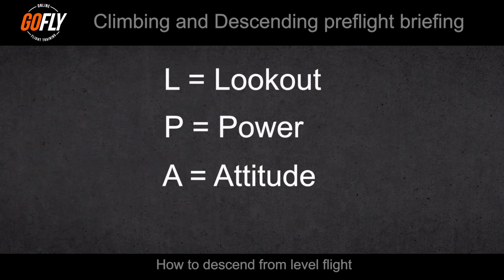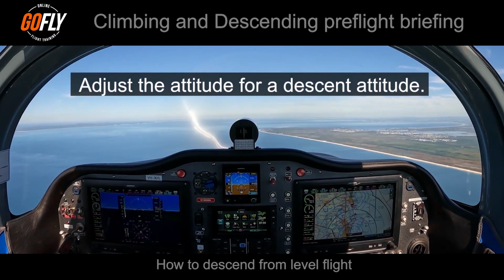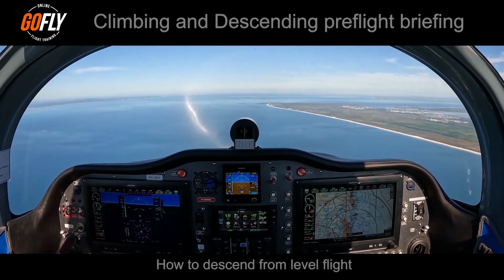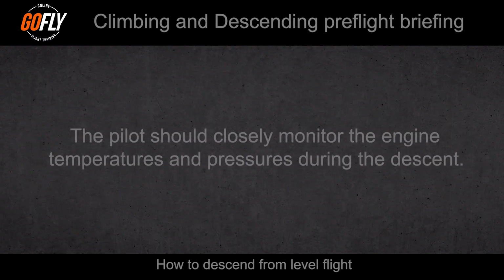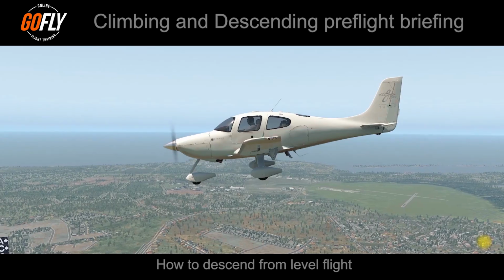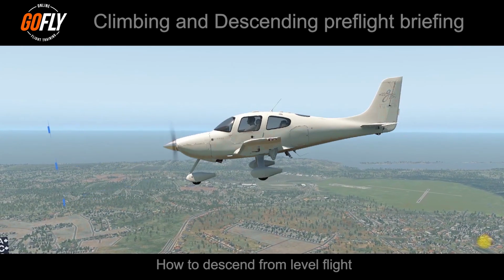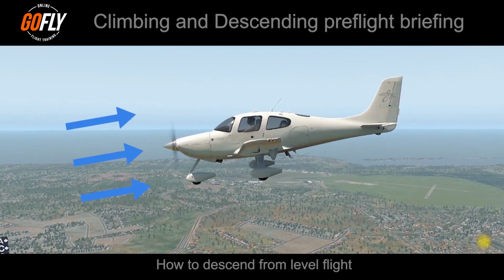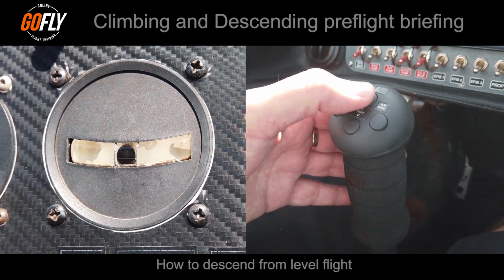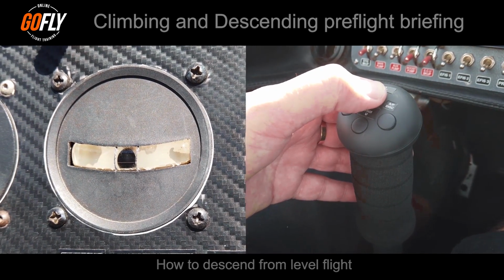A is for attitude. The pilot would then adjust the attitude for a descent attitude. Normally this would be the same as the cruise airspeed for a cruise descent. The pilot would monitor the temperature and pressures during the descent. Remember, during a descent we have a lower power setting and more airflow flowing through the engine, so overcooling is a possibility. T is for trim. Once the attitude, airspeed and rate of descent has stabilized, trim the aircraft and ensure the aircraft is in balance.